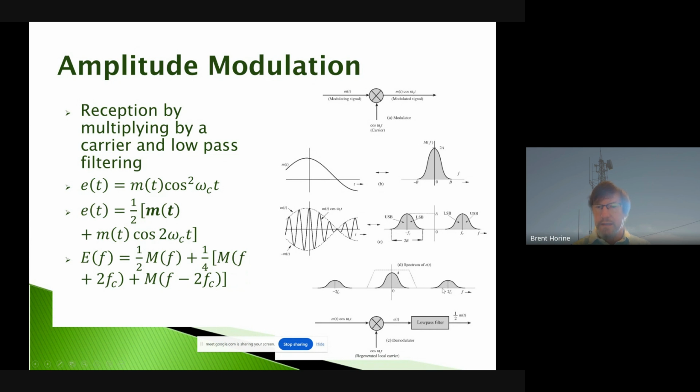We have these plus 2fc and minus 2fc, and then we have this baseband or information signal. So we've retrieved this. There's some scale factors involved that's trivial to deal with, just this 1/2 type of thing. But we filter that out, and we lose that energy. That's gone, but we've retrieved that.